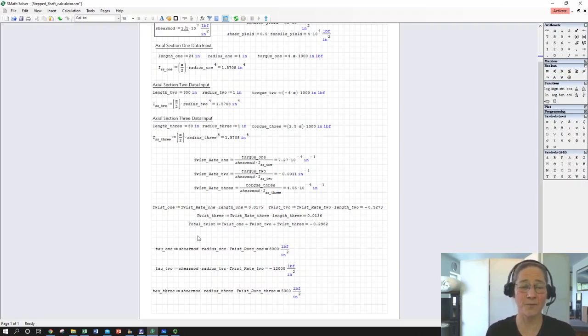Where you would step up from this would be basically using either Excel or using a program where you would calculate thresholds with given constraints. What is the smallest shaft you could have? What is the largest torque you could apply? So, solving for those extremes as opposed to kind of having to do it hunt and peck, iteratively calculating. But at the very least, you do not run the risk of fat fingering something on a repeat calculation.